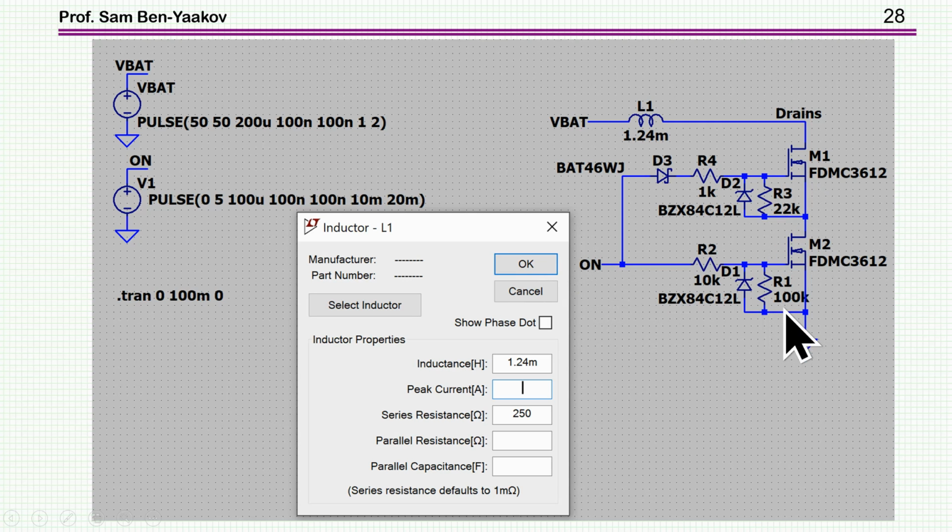Now I've chosen two values. Here, the impedance when the thing is operating is 10 kilo ohm, okay? So it's okay, although it's a rather slow operation because the gate current is fairly low, but it's okay for this application. Now, here I've chosen 22 kilo ohm, and the reason is that while here we have a 10K for discharge, here the discharge of the gate charge will be through this resistor. Now, if this resistor is large, then it'll take a long time. And this is just a compromise that I've decided on to have this 22K